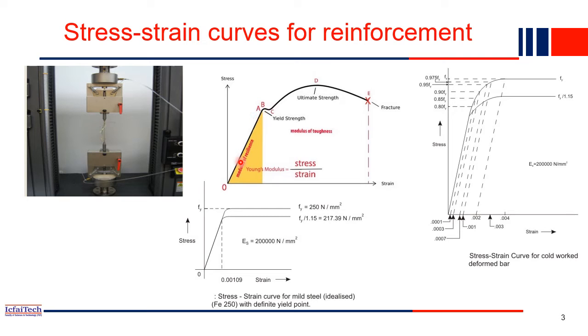So our structure, we will construct a structure. Our structure should be lying in this lane, in this position, elastic position. After A, basically the structure, or the steel, gets yielded, meaning the inelastic behavior starts coming. Up to point A it is a linear behavior. After A you see the inelastic behavior, because this curve is not linear, right? It is curvy, non-linear. So non-linear behavior will start after the yield point.